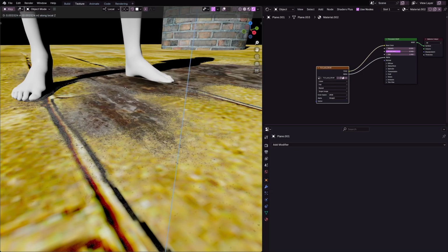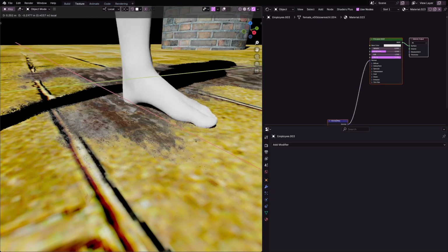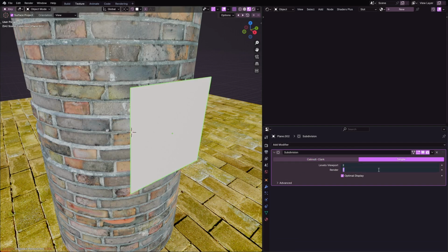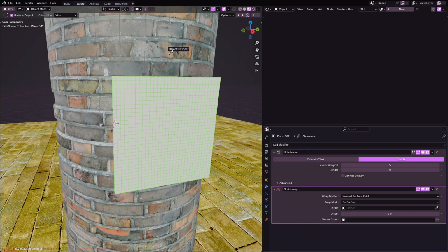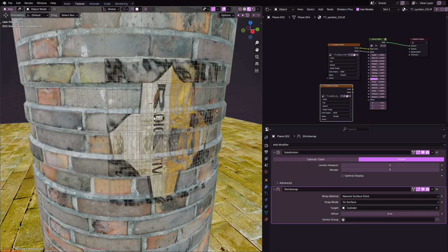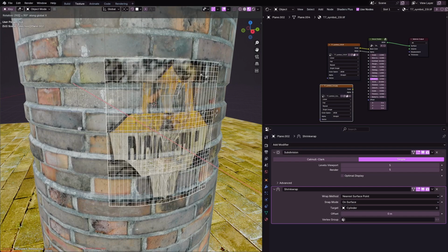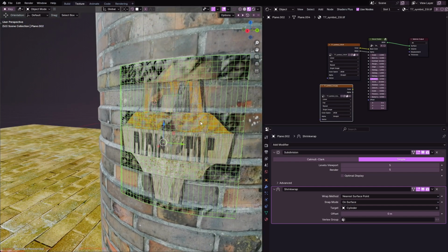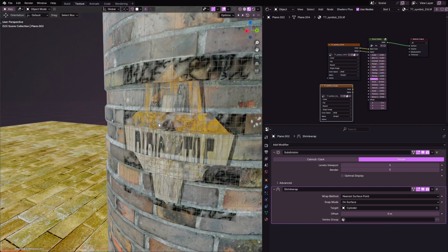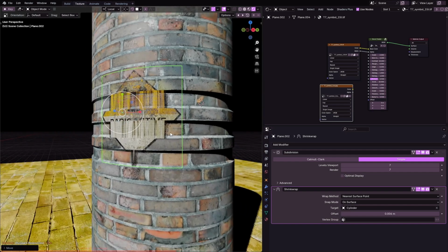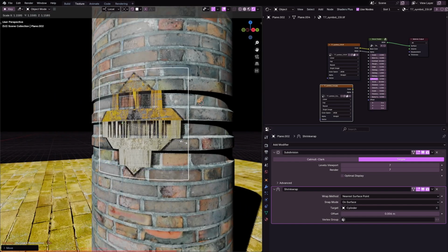And don't get me started on uneven surfaces. The closest you get is to subdivide the plane a hundredfold and use a shrink wrap modifier. It works, but not without the risk of Z-fighting. It doesn't even solve the problem of literal edges. Plus, you can't even bake these decals into textures, no matter how much you grovel. Blender, give it to me, please. No, you can't bake it out.